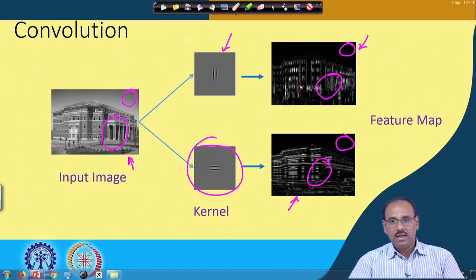What we said is that convolution is the response of a linear time invariant system, or a linear space invariant system, to the input signal presented to that LTI or LSI system. We have also said that LTI or LSI systems are completely characterized by their impulse response.